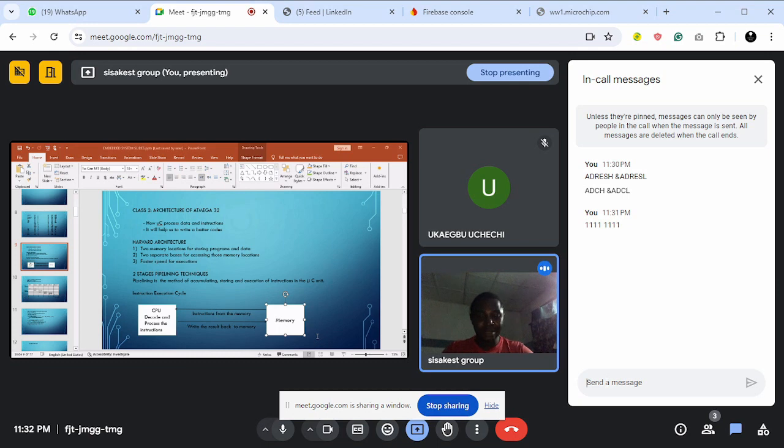Or let's take 8, for example. If the value is going to be 8, then I expect this to be in my memory. This is 8 now. Now, if the value of the temperature is greater than 8, do something, maybe turn off a light and turn on a light. Of course, you can now be looking at the general purpose register. For example, of course, we can look at DDRA.